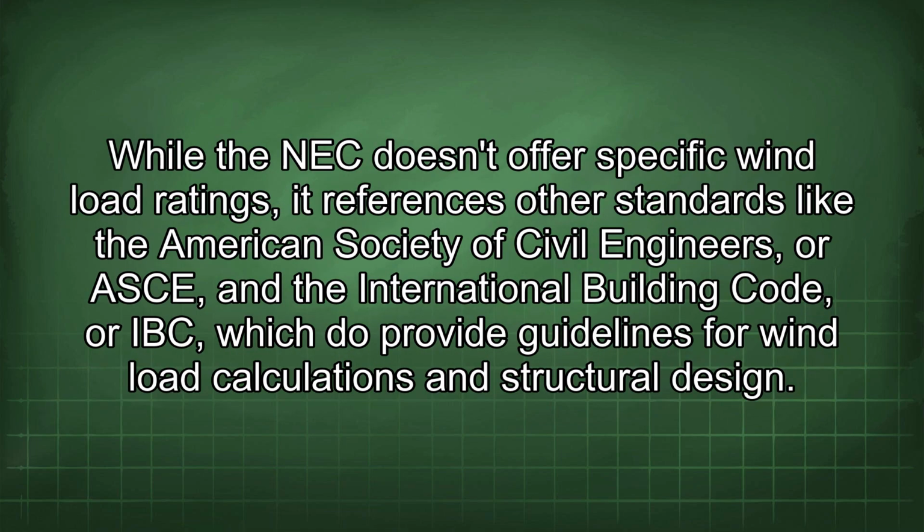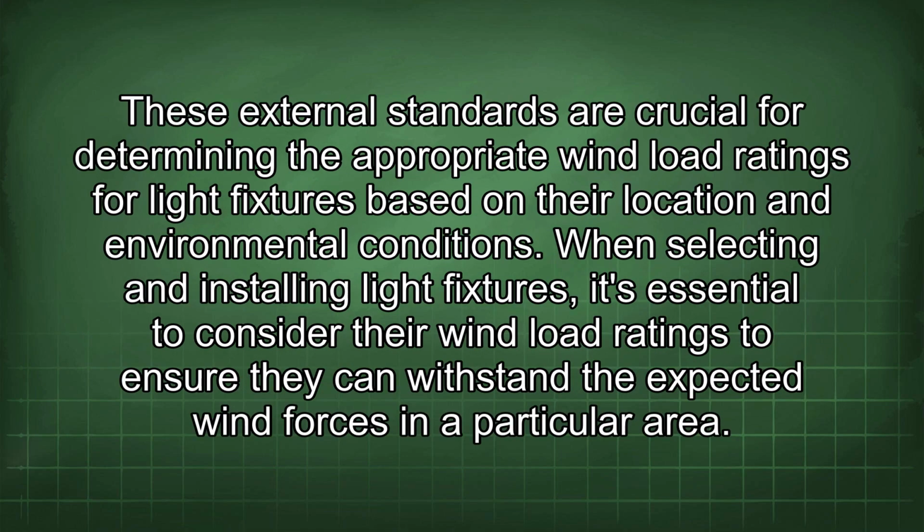While the NEC doesn't offer specific wind load ratings, it references other standards like the American Society of Civil Engineers, or ASCE, and the International Building Code, or IBC, which do provide guidelines for wind load calculations and structural design. These external standards are crucial for determining the appropriate wind load ratings for light fixtures based on their location and environmental conditions. When selecting and installing light fixtures, it's essential to consider their wind load ratings to ensure they can withstand the expected wind forces in a particular area.